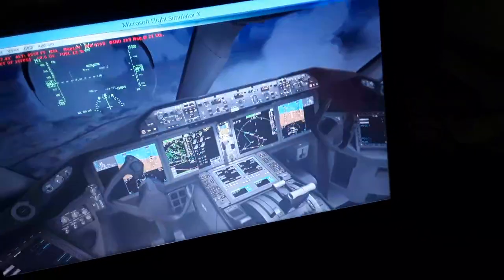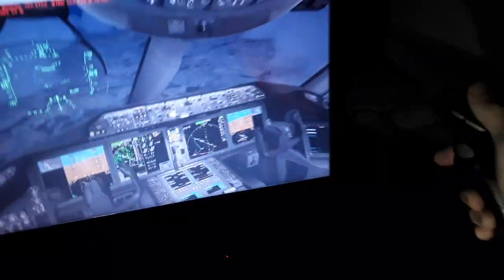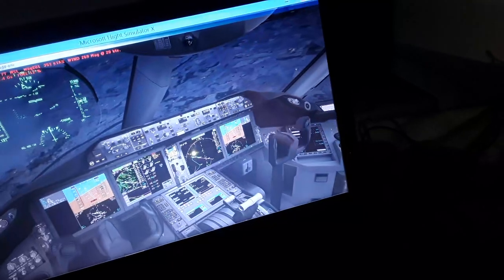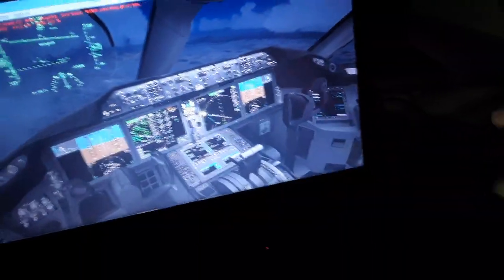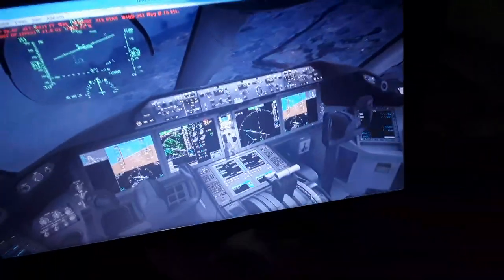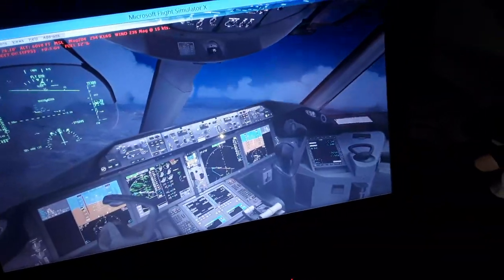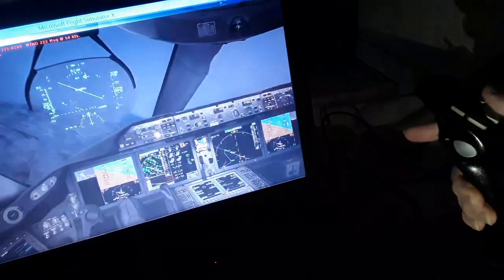So we are almost aligned with the runway here. We are a little bit higher, as you can see, so we use landing gear down. Align also with the runway as we are descending. Also some flaps. And we have the runway here for alignment. Use left rudder over here.